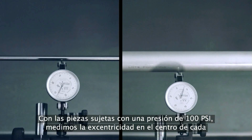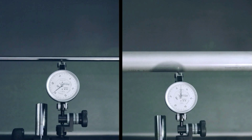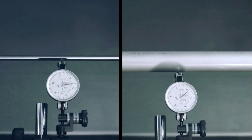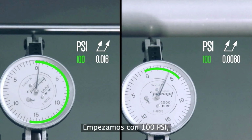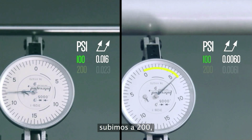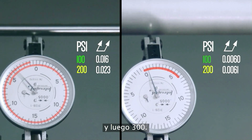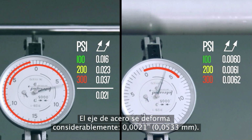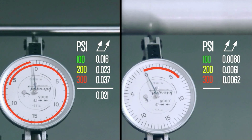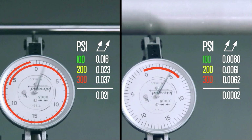Starting with the parts held at 100 psi, we'll measure runout at the middle of each part as we make 100 psi tailstock pressure increases. Okay, starting at 100 psi, increasing to 200, and then 300, the steel rod deforms significantly by an additional 21 thou. Its neighbor, the aluminum tube, deforms by only 2 tenths.